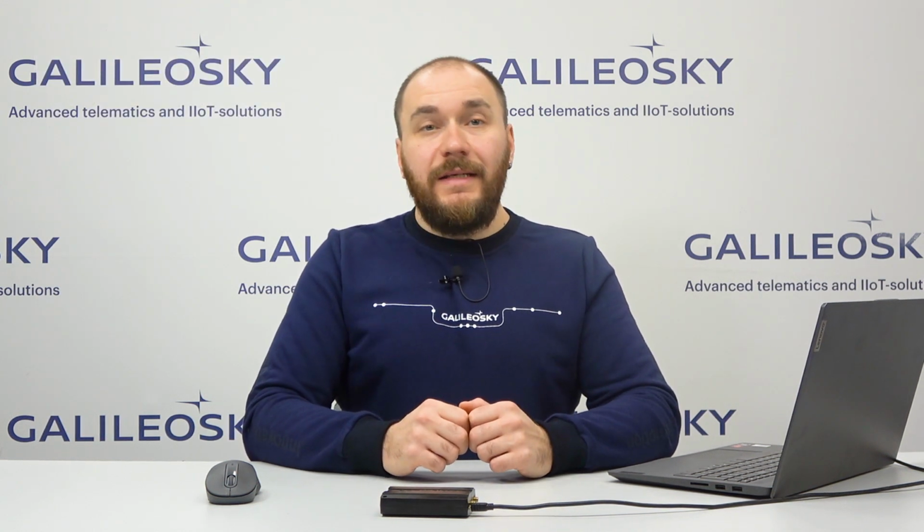The Modbus-TCP server features are available on Galileosky 7X Wi-Fi hub trackers, starting with firmware 44.4, and Galileosky 10 hub devices, starting with firmware 1.1. The configurator should be version 5.2.01 and higher. First, we need to download the EasyLogic Modbus-TCP server algorithm to the tracker.